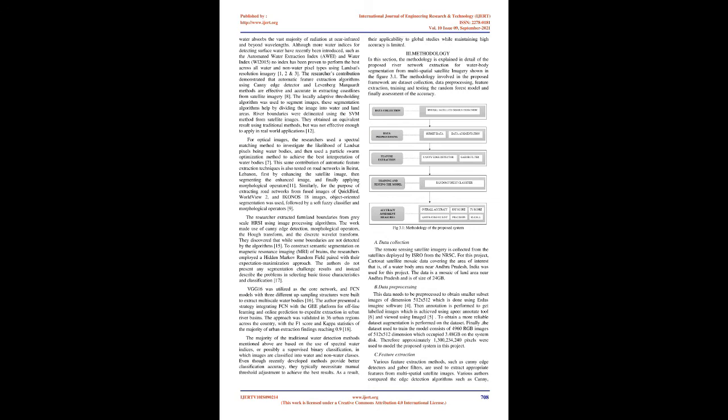Existing methods for detecting surface water from multispectral satellite data are based on the fact that water absorbs the vast majority of radiation at near-infrared and beyond wavelengths. Although more water indices for detecting surface water have recently been introduced, such as the Automated Water Extraction Index, AWEI, and Water Index 2015, WI2015, no index has been proven to perform the best across all water and non-water pixel types using Landsat's resolution imagery.